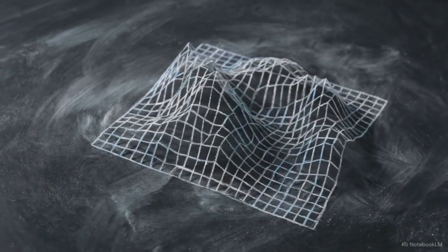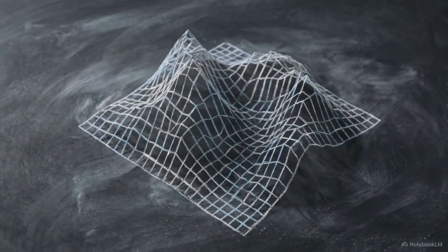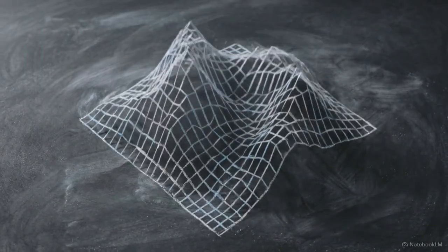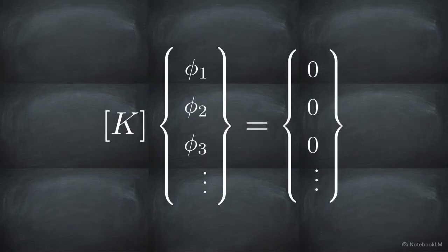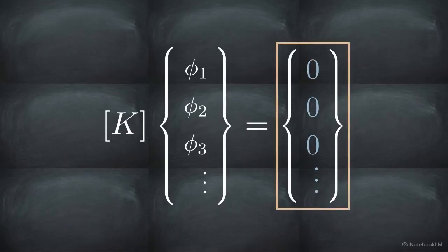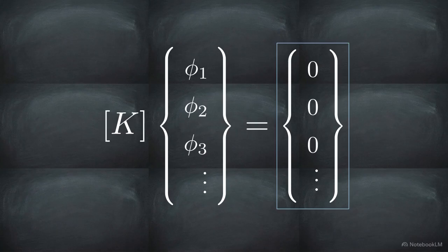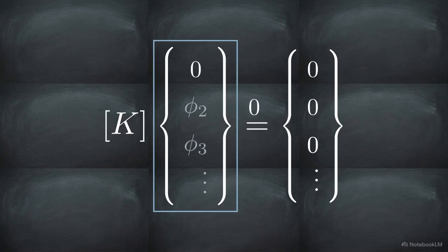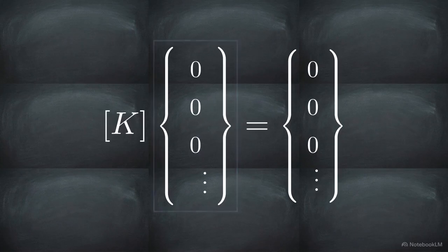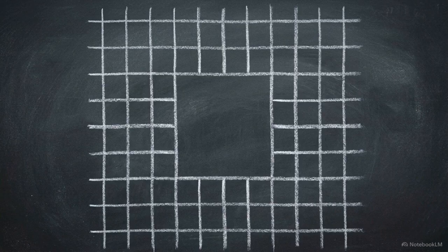Imagine running a complex, three-dimensional topographic simulation, only to watch the entire mesh instantly flatten into a featureless plane. That failure happens because assembling the baseline Laplace equation naturally results in a right-hand side vector of exactly 0. If we run the calculation as is, the math perfectly balances out, giving us a completely zeroed vector for every unknown node. In numerical methods, this self-canceling dead end is known as the trivial solution.